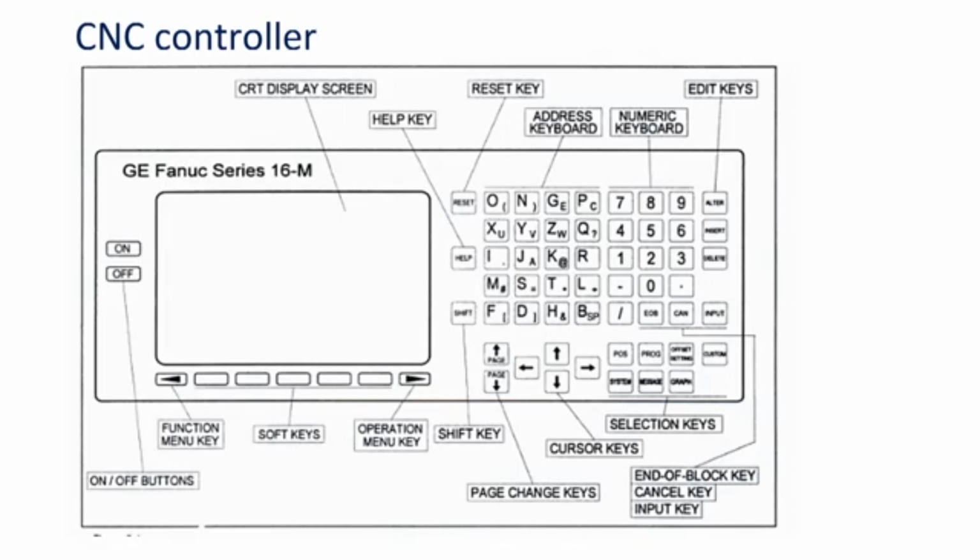Now, the assembly of a typical work table. As we have already seen, we are using a lead screw over which the nut is mounted, and over the nut there is a work table. The precision movement of the work table all depends upon the accuracy of the nut and lead screw relative motion. So, the lead screws are operated by using a servo motor.